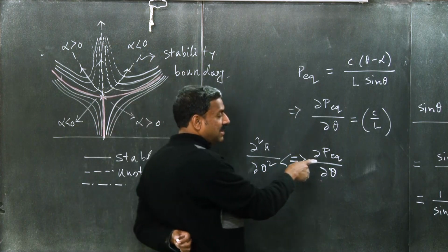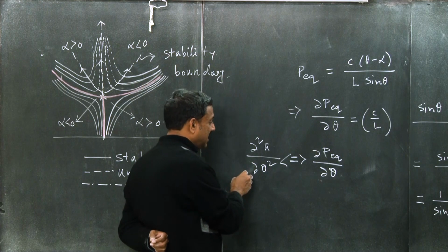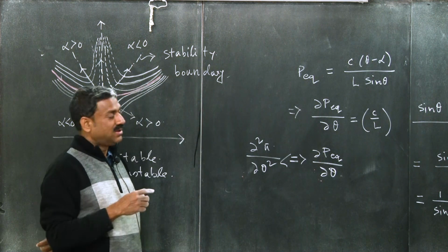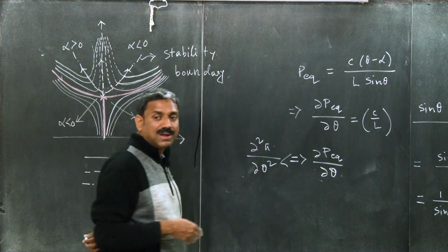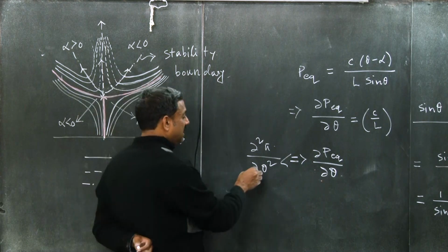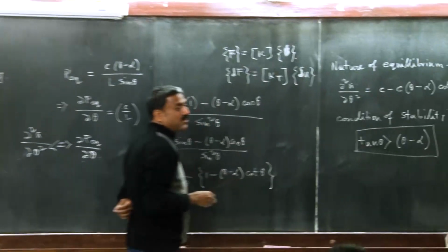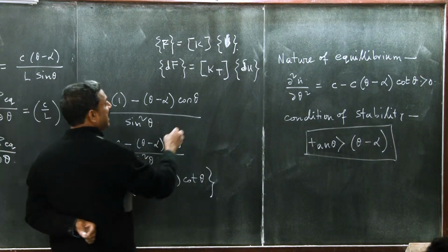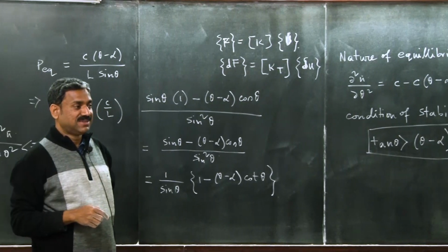So whether it is the Hessian of the potential energy functional or the gradient of the force with respect to theta, both are equivalent simply because they correspond to incremental equilibrium equations, and they basically ascertain the determinant of kt, the tangent stiffness, okay.